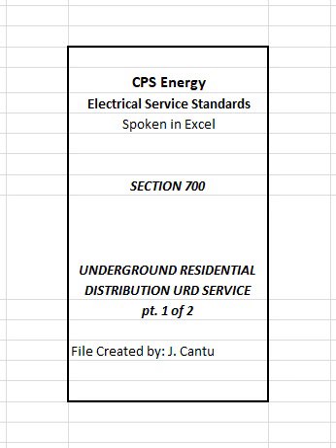704 Service lateral conduits. Service laterals shall be totally enclosed in conduits. All conduits, elbows, and couplings shall be furnished and installed by CPS Energy from transformer or secondary enclosure to meter loop. The conduit system shall be continuous except for watertight couplings, refer to Figure 701.